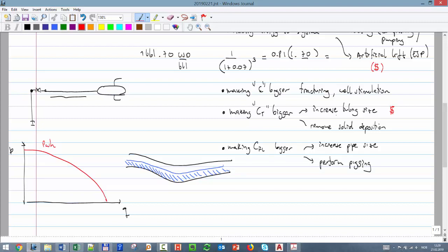Okay, and P of the flow line might look something like that. Okay, so be careful. Changing the flow line will give you a higher plateau, it will give you a longer plateau. But if this curve is already very, very flat, and you are going to propose to use a bigger pipe, really the increase in rate is not going to be worth the investment.